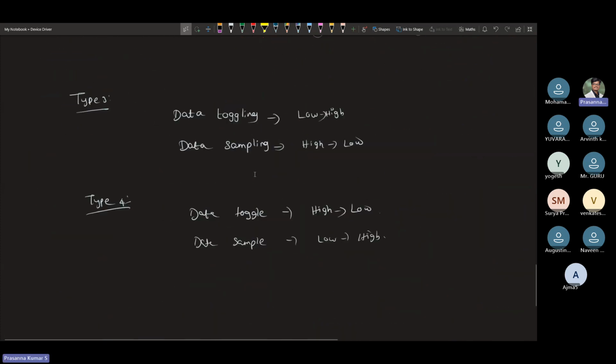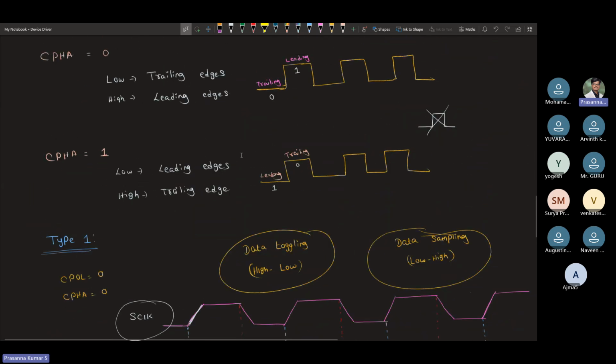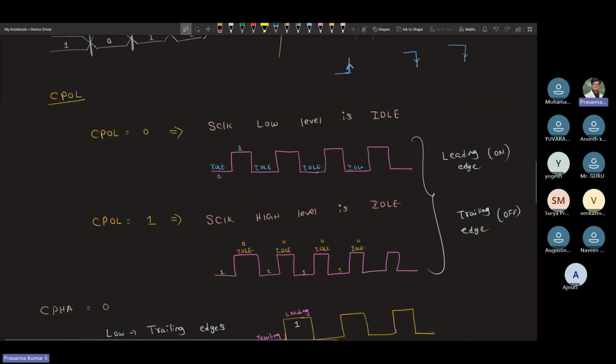So that is what this SPI communication is, how this data will be transferred. Now in STM, what we will do is simply click a drop down box and select this clock polarity as 0 or 1. It's a simple step. But for selecting that, why we need to select this clock polarity as 0 or 1, we need to know all these things.